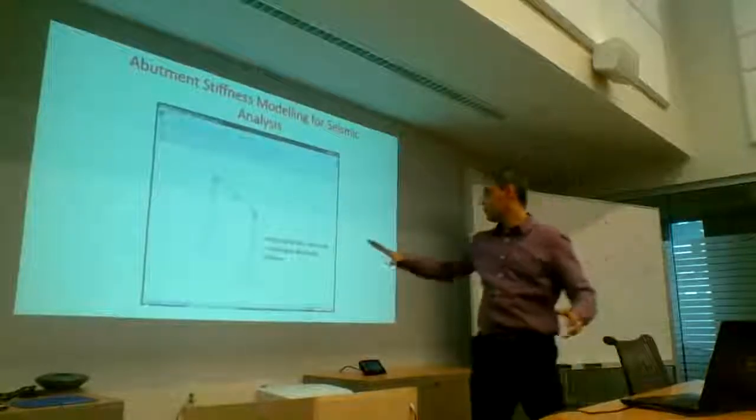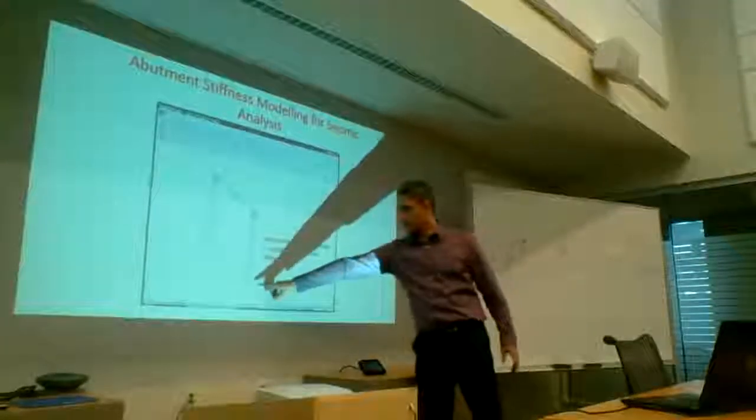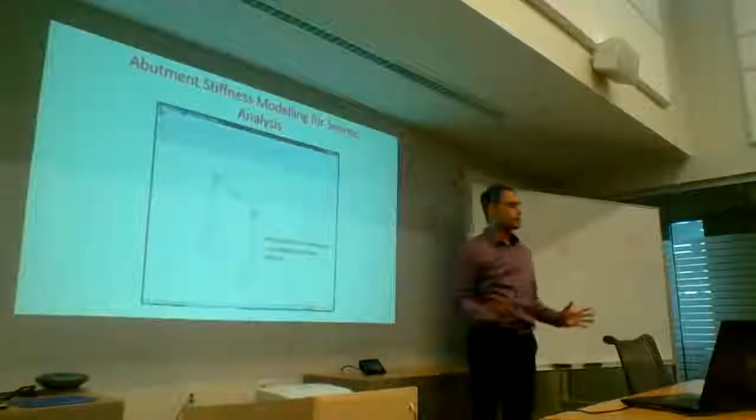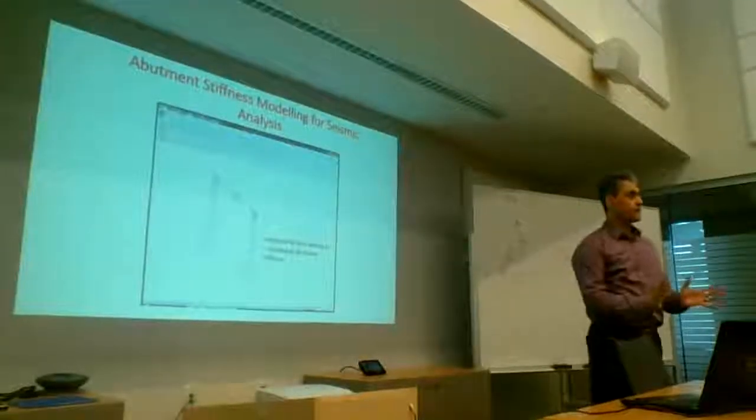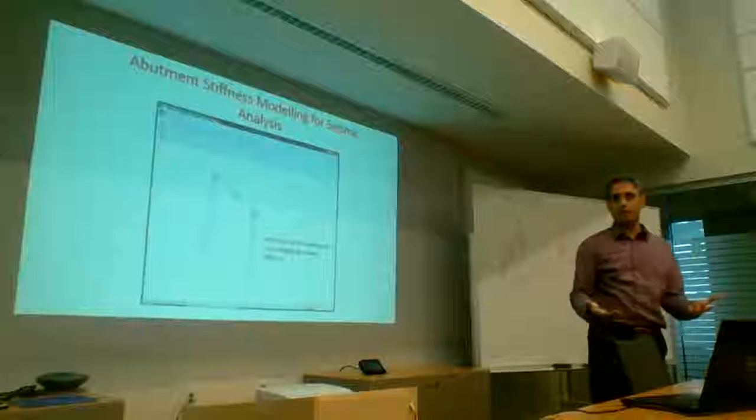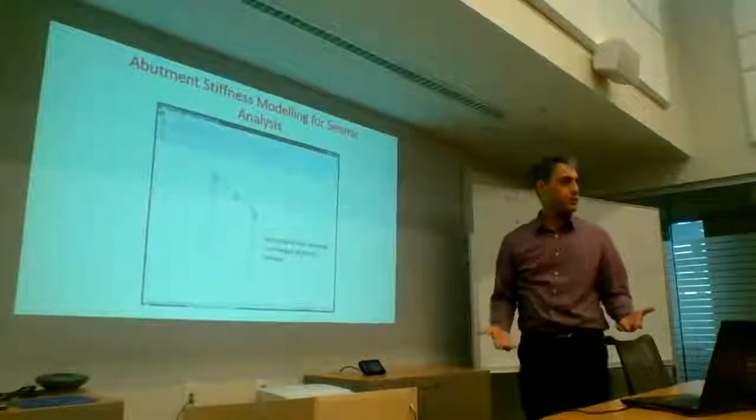And then when you go to converged, instead of 13,000 something, you're at 9,000. So your abutments are definitely helping you. That's a drop of about 40%. So your column sizes are going to be a lot more manageable.